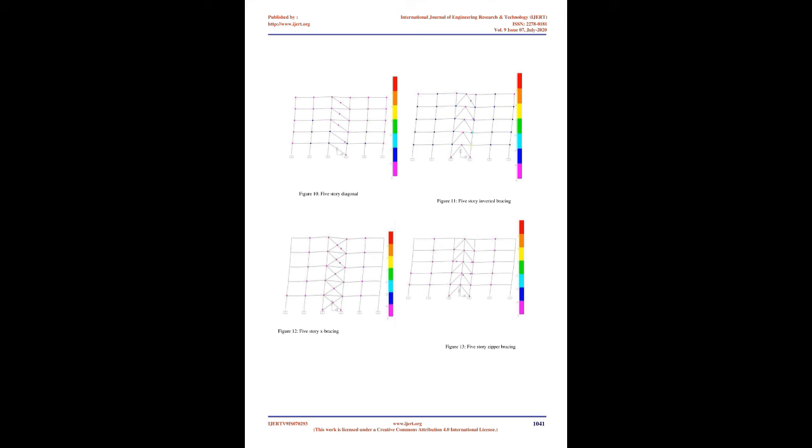9. Interstory drift. The interstory drift ratio is the maximum percentage drift between two floors divided by their story height. The result of this study shows that inserting the steel bracing system decreases the peak interstory drift. Story drift for both braced and unbraced structure is shown in figure 9. The result shows that the upper stories decrease in a fairly linear manner. Top floors have lesser story drifts compared to lower story drifts because of their low displacement values when the steel bracing is inserted, and the interstory drift of the first story is less than the second story interstory drift, which should not have been the case.